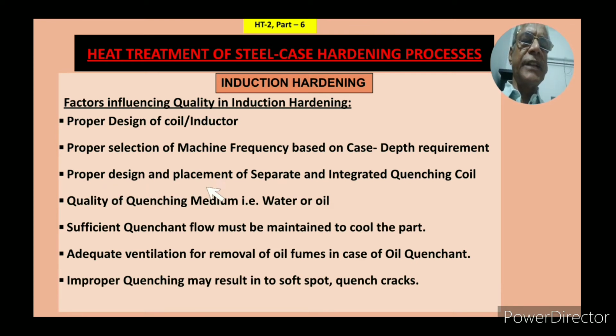Then proper design and placement of separate and integrated quenching coil. Wherever you are using a separate quenching coil or an integrated quenching coil, their placement must be properly designed, where to place, because it travels and at a particular time the part has to be quenched. So where it is to be placed, this has to be decided very carefully.